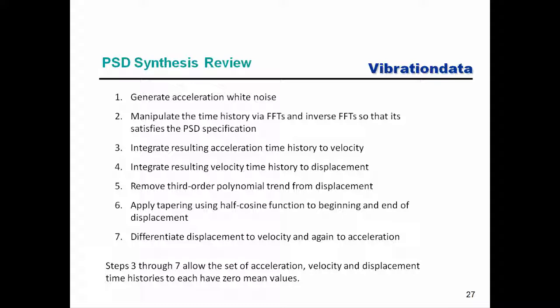So for step 7, I take that displacement from which the 3rd order trend has been removed, and also with the tapering. When I say tapering, if any of you have played around with acoustics or sound processing, in the acoustic world that would be called the fade in and fade out.